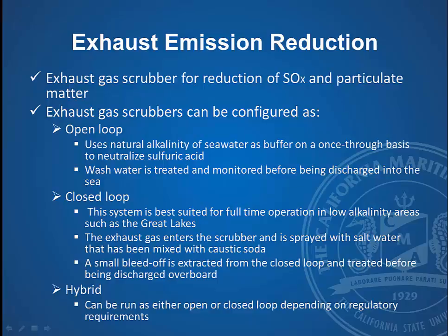You will have trays within the exhaust gas scrubber, and those trays typically will have either rock or what almost looks like a ping pong ball, and the exhaust gas is coming up through that media, and you're spraying, I guess if you want to call it sprinklers, salt water onto that to cool it and to saturate it so that the sulfur will be carried away with the salt water and also the particulates.